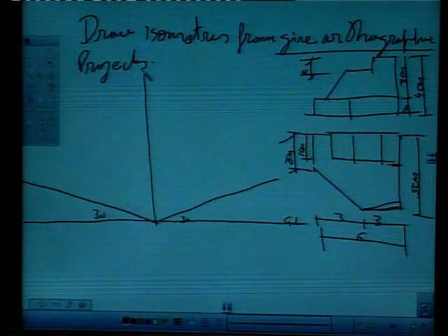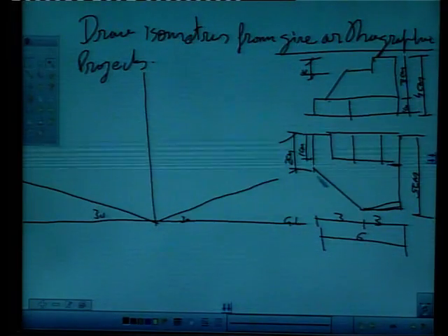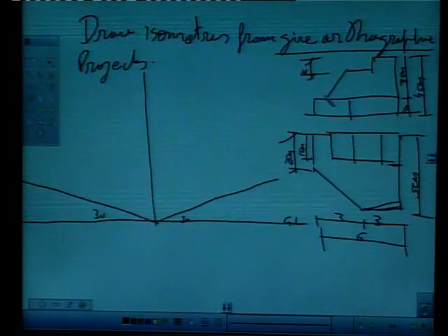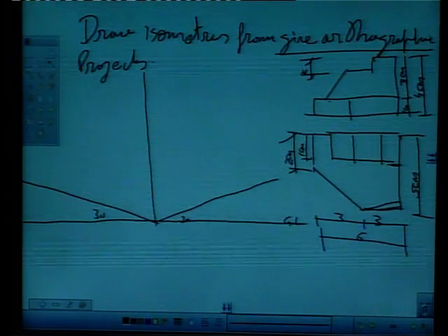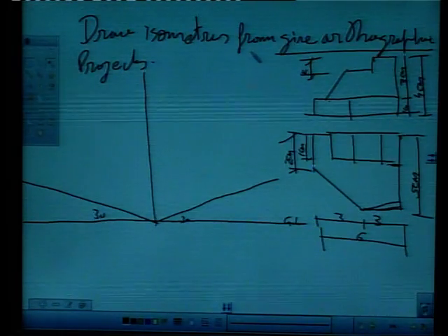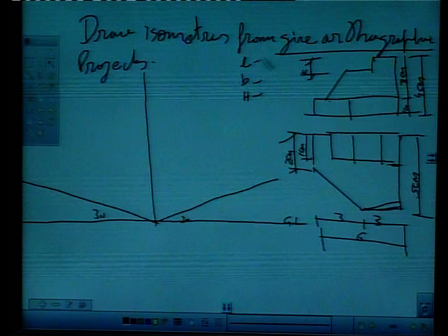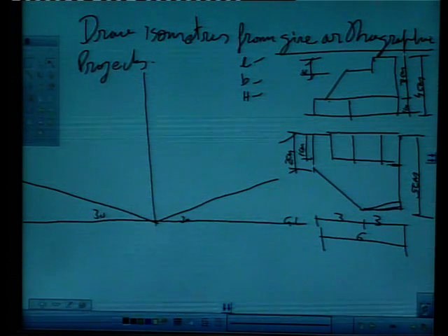In this example also we have so many non-isometric edges, like this edge is non-isometric, this edge is non-isometric. So how to draw the drawing? The right way to draw this is, we will work out maximum length, maximum breadth and maximum height. That means we will enclose our drawing or object into a cuboid.